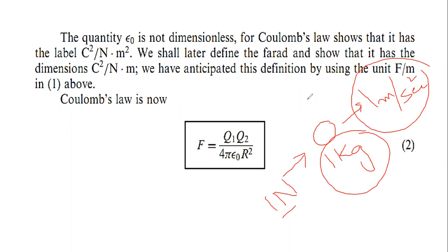So it is the force required to give a 1 kilogram mass an acceleration of 1 meter per second square. And if we represent this 1 Newton force in pounds, 1 Newton is equal to 0.2248 pound.